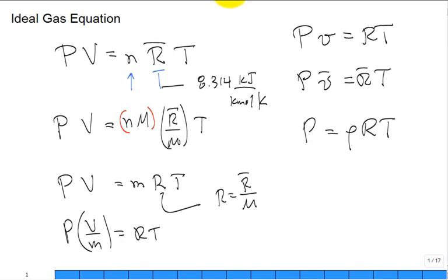What's a common mistake? Somebody will be given a temperature like 20 degrees C and they'll put in temperature 20. What do we know? Must be absolute. And the pressure, less common, make sure it's absolute pressure, not gauge.